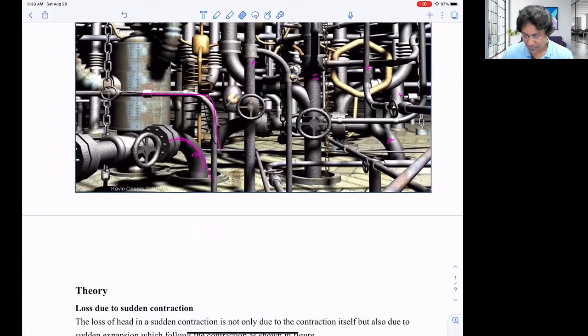Okay. So why is this important? Because we need to carry water. If we just consider water as a fluid or liquid for this case, we want to carry water from a distribution system to the household or industry or anywhere, right? So what do we need? We need to use a bigger pipe from the source, and then gradually we'll change our pipe diameter, and up to the tap of water we'll use a very small diameter pipe.